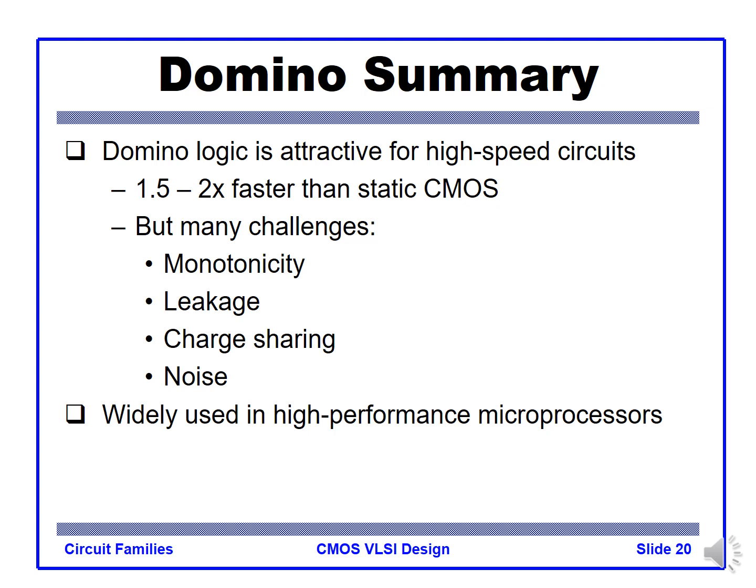But this kind of circuit is widely used currently in high-performance microprocessors like CPUs. It has arithmetic building blocks like adders or multipliers, circuits that require very high-speed operation. In that case, you may use such a domino circuit.